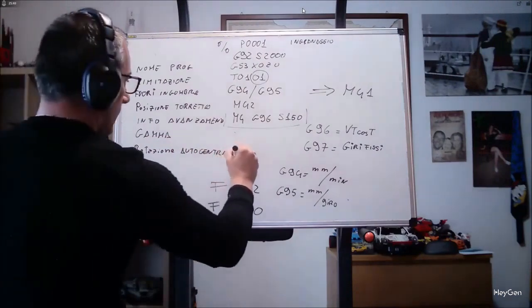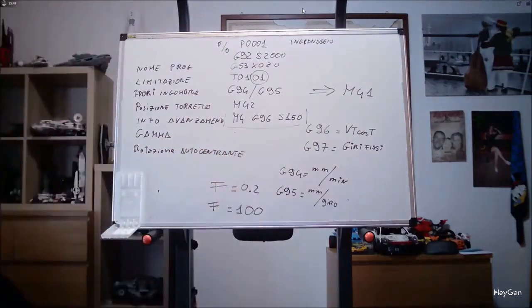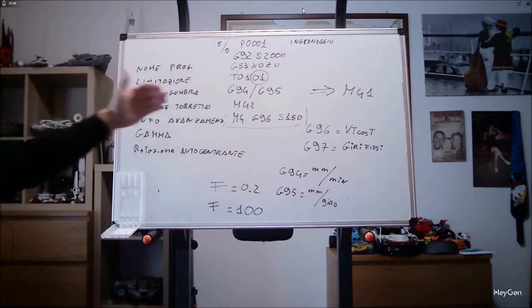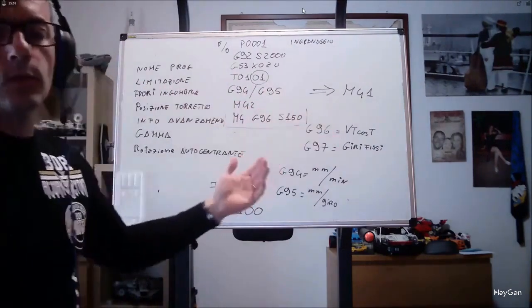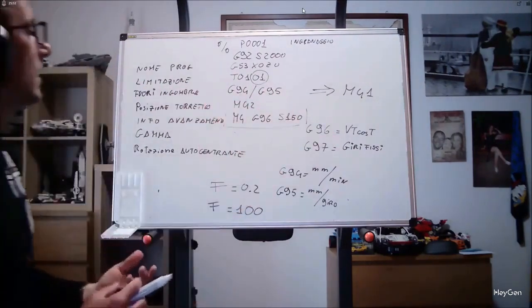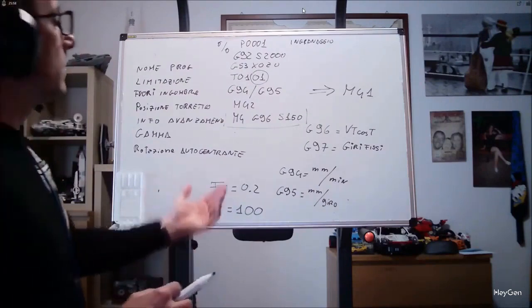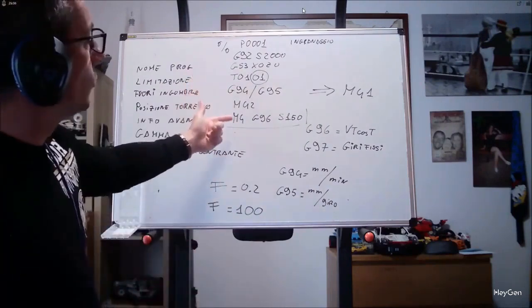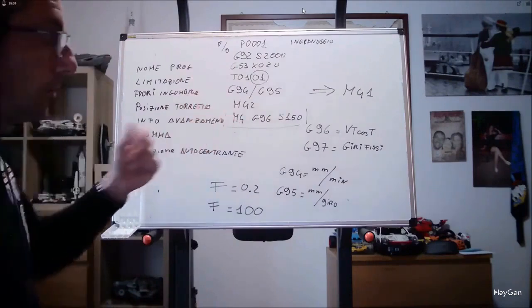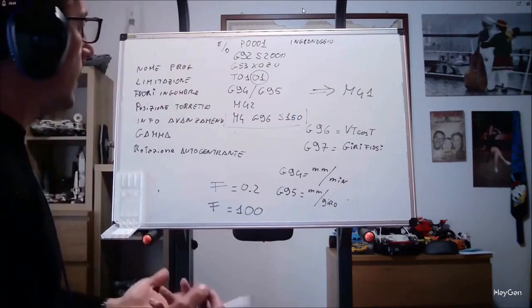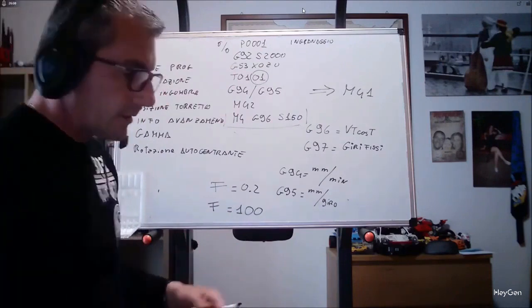These are the preparatory functions that our machine will always need before starting to move the axis. Without these, the machine will hardly move the axis. Attention, with G94 the axis moves even if the spindle is not rotating, so be careful when using it. It's more of a really gripping function.